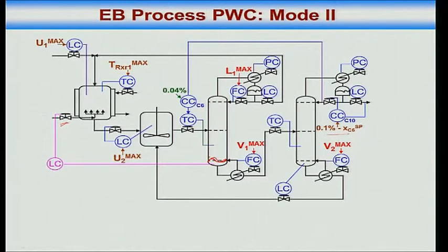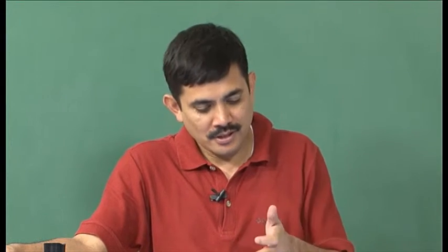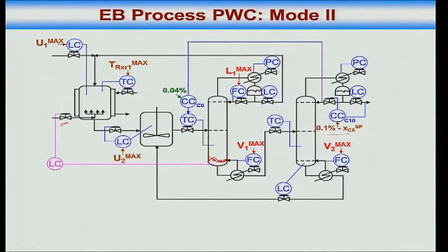But for the residence time problem, if I had a plug flow reactor, in fact we have done simulations and shown that if you have a plug flow reactor, residence time is not an issue. You make a change here, right, because the flow is compressible flow essentially. So, but for the large residence time in the reactors, this scheme would have worked. It turns out that for this process, it won't work because the total reactor residence time is of the order of 2 hours. Had it been of the order of 5, 10, 15 minutes, it would have worked.